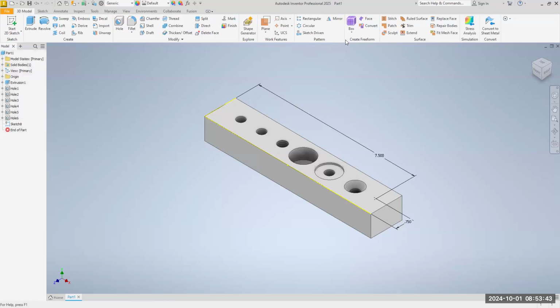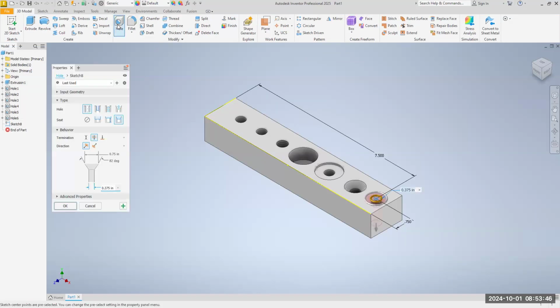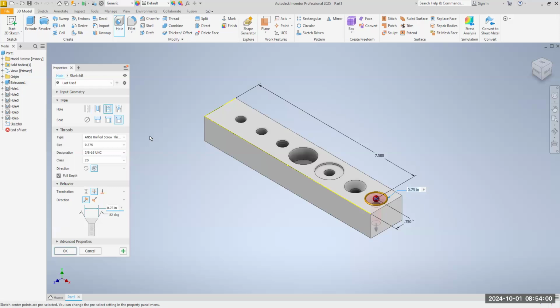Finish the sketch. Go to hole. And this one's a little tricky, okay? So we're going to have a threaded hole first. We're going to have a threaded hole like this. And I've never seen a hole like this. We have a threaded hole and we have a counterbore combination. Okay, and the size of this, for the tapped hole, is a 5/16.